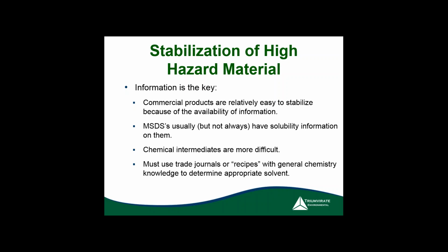Diluting the material is a common misconception. If you have a peroxide former, just diluting it down does not remove the peroxides. All you're doing is separating the solvent and the peroxides, and actually you can concentrate the peroxides and make it actually more of a hazard because you're concentrating those peroxides. So dilution is not the answer. So to get all that information and make that determination on the front end is extremely important prior to handling the material. These are all steps that we go through before we handle anything in working with our clients.